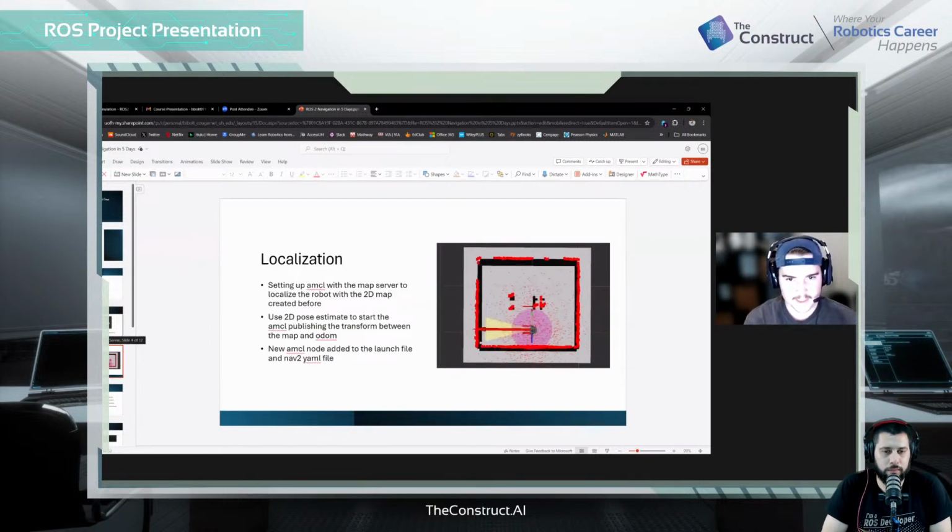Next, for localization, we have to set up AMCL for the map server to localize the robot with the 2D map. We use a 2D pose estimate so that AMCL can then communicate the transform between the map and ODOM. And then the new AMCL node will be added to the launch file so that they can launch together.